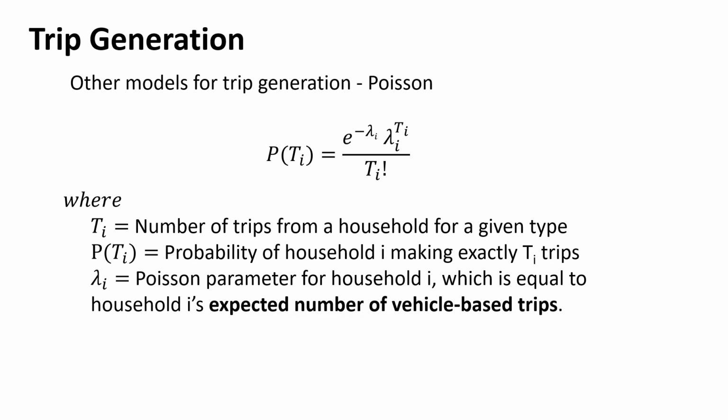What's the probability of 1 car arriving during that minute? What's the probability of 2 cars arriving? If you remember back to that section we were doing in signals, that's where we used Poisson before. And it works well if you know what the average rate is. The thing they like about this with trip generation is that if you want to figure out the probability of a discrete number, 0, 1, 2, 3, an integer value, that's where Poisson jumps in.